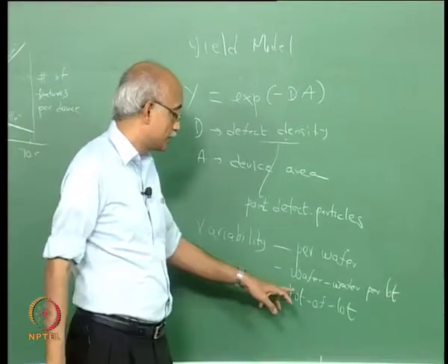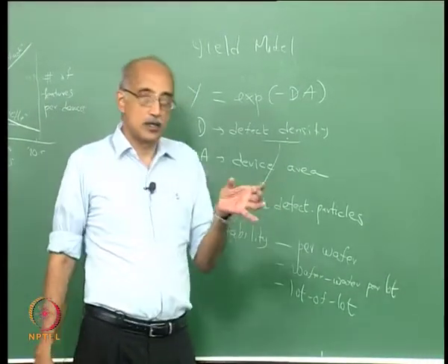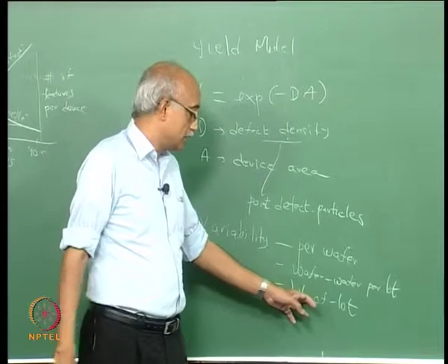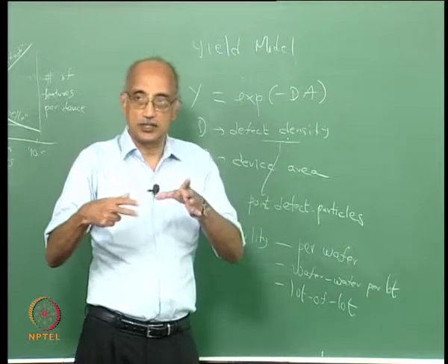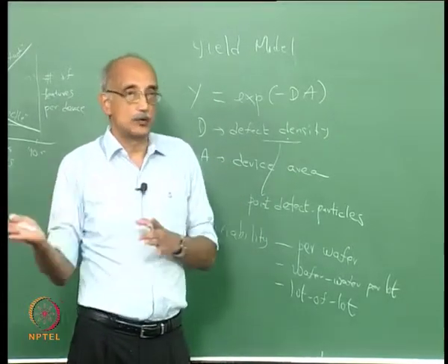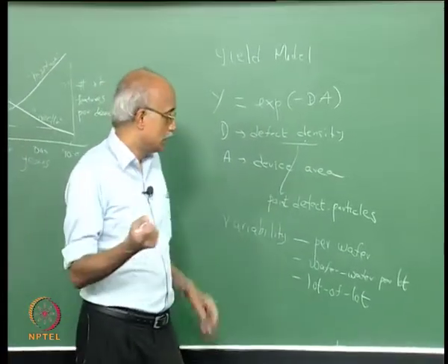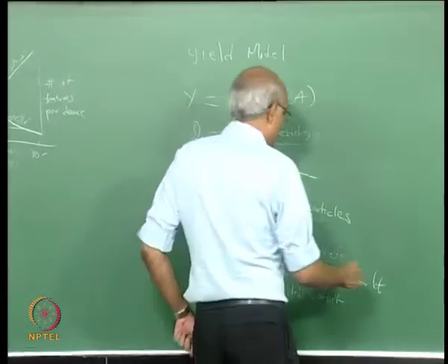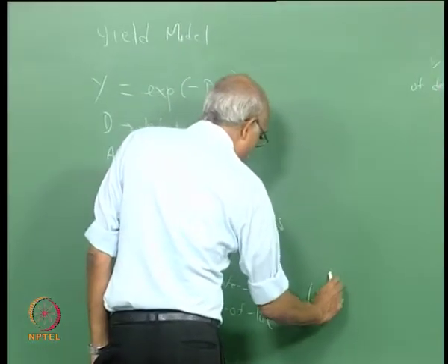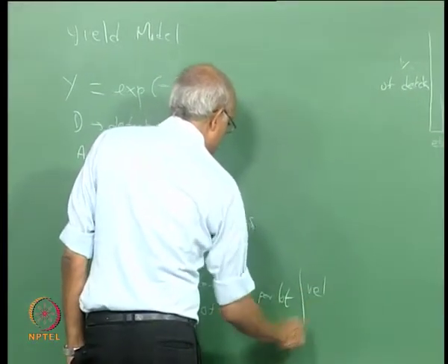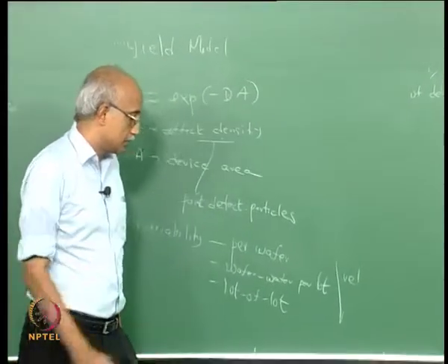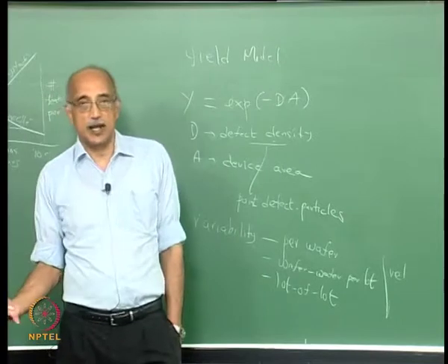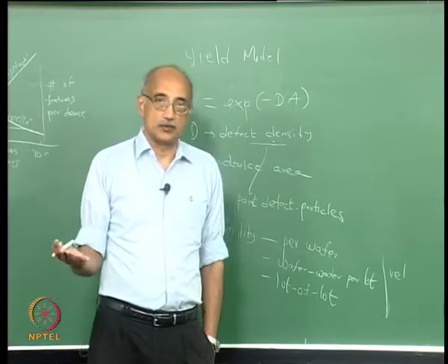And similarly, if every wafer in one lot is very similar, but there are variations from lot to lot, then you can keep several batches of wafers as being good and only throw out the bad batches of wafers. So, in terms of net reliability, the impact is very, very different, and the reliability essentially increases in this direction, because these two situations give you the ability to screen out the bad stuff and only ship the good stuff.